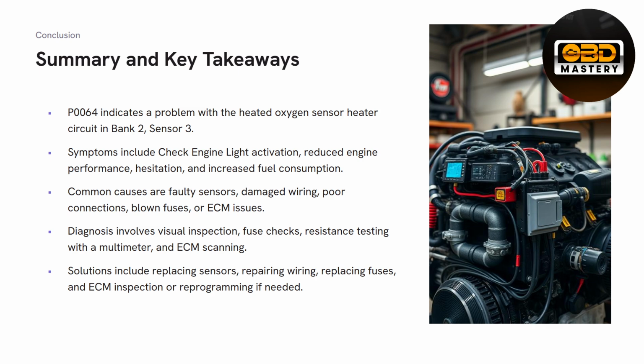Summary and key takeaways: this problem has to do with the heated oxygen sensor heater circuit in bank 2 sensor 3, and symptoms are the check engine light and much more. Common causes are blown fuses, the ECM, faulty sensors, and much more. Diagnosis involves a visual inspection, fuse checks, resistance testing with a multimeter, and even ECM scanning. Solutions include replacing sensors, replacing wiring, replacing fuses, and ECM inspection or reprogramming if needed.